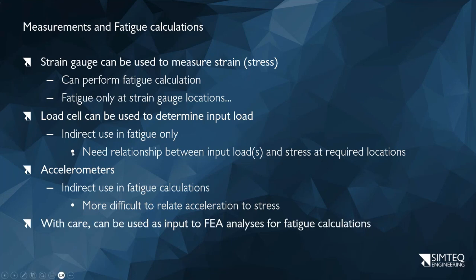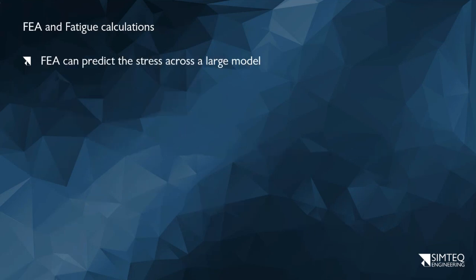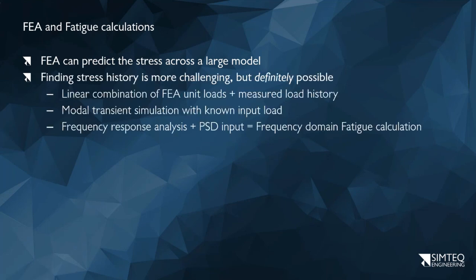Okay, so if you're careful, you can use some of the measurements also for inputs into FEA and do the fatigue calculation in there. So it's entirely possible. It's not too hard. It's just a couple of things you have to double check that you're doing correctly. If we want to do it in FEA though, the advantage in FEA is we can predict the stress over pretty much the full model.